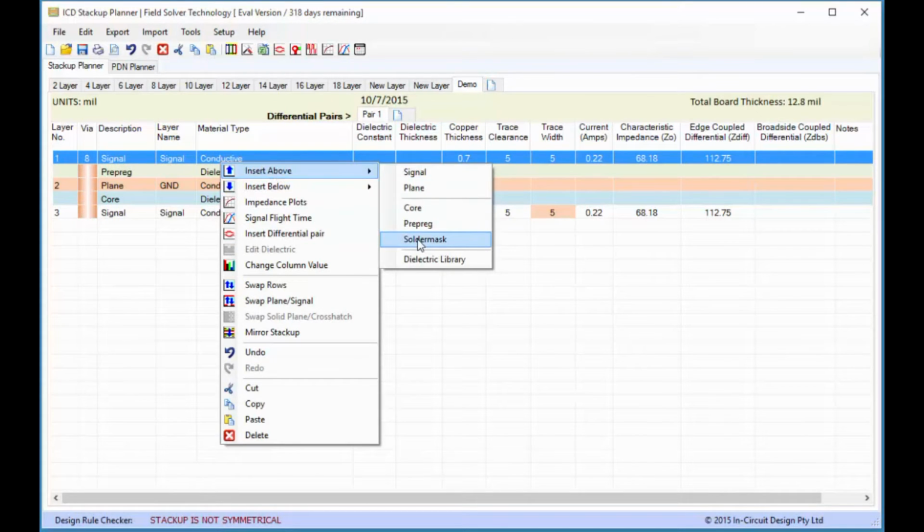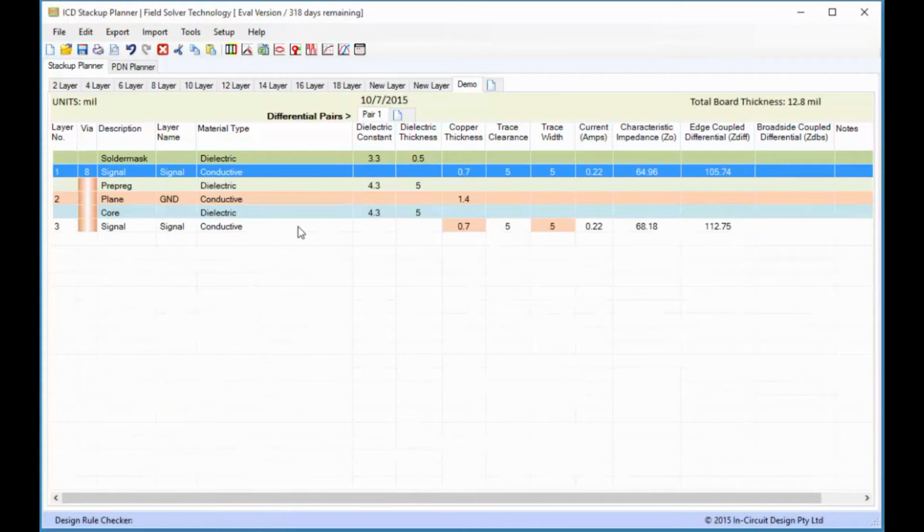And then lastly, I need something that is called the solder mask. The solder mask is really there, number one, to cover over the copper traces that are not requiring any type of solder. So when we put solder on our pads, we don't want to wick down the traces. That's first and foremost, because otherwise we'll lose all our solder. But secondly, we don't want our copper to be exposed to the air, because copper has an amazing way of reacting with the air over time, and obviously it's going to cause some reliability issues. So we want to make sure we do have a solder mask on the top over here.